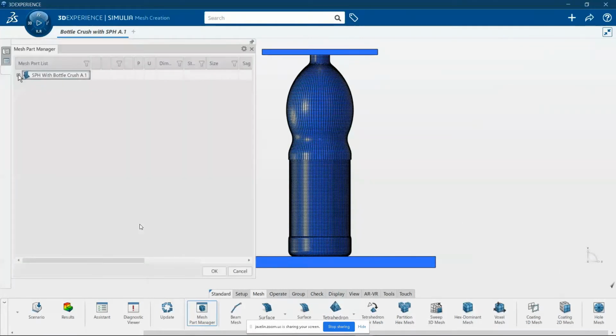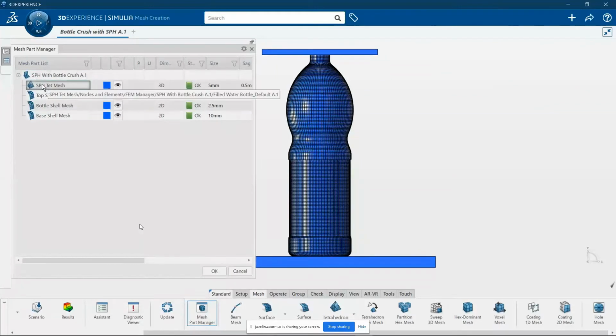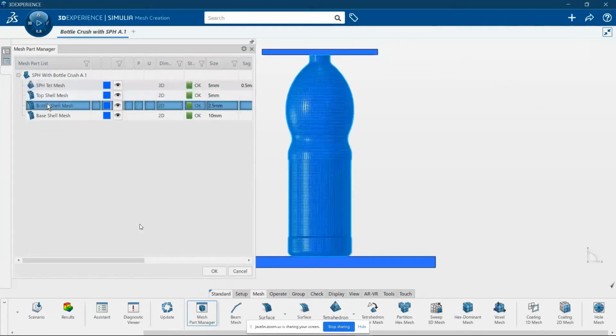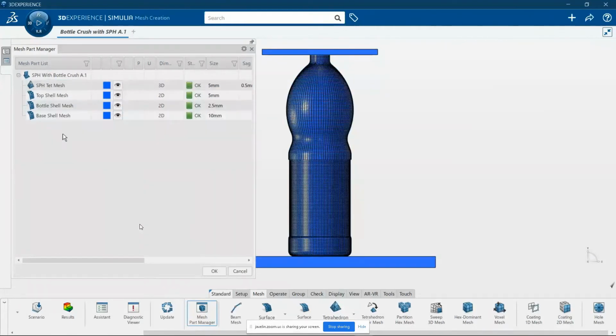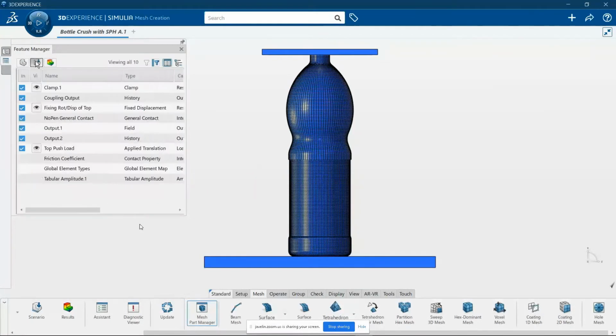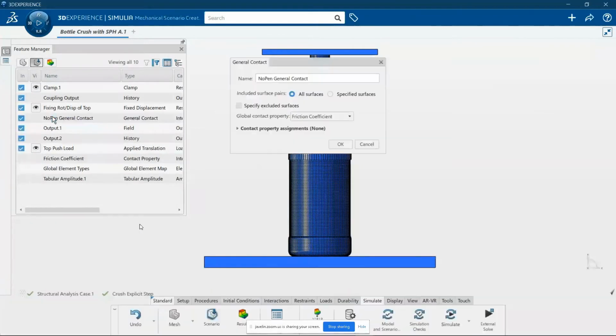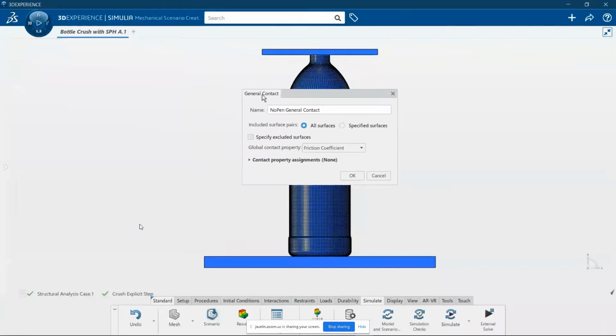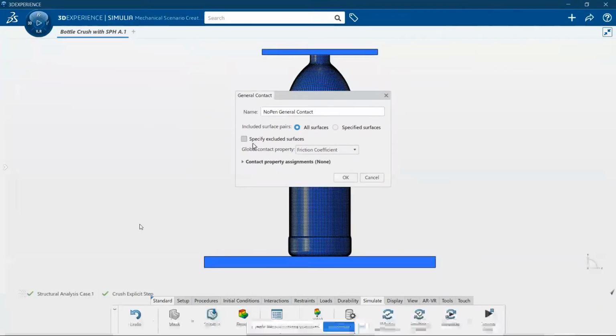So these are brick elements. I can use parabolic or linear bricks. If you're using a hyperelastic material, there are H elements that are available here. There's some reduced order integration elements. There are a lot of bells and whistles that, depending on the type of analysis you're doing, we can do just a lot more. And in this case, actually, an FD03, which is kind of like a service pack that was just released, now we can do axisymmetric analysis. So I could have modeled this as axisymmetric.